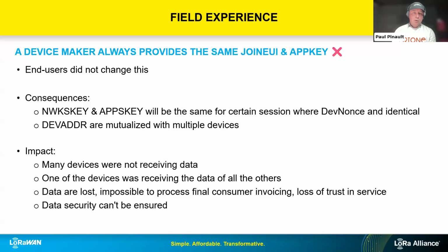And maybe you can complete this part, Julien. I mean, to obtain this DevAddr, I say it's the LoRa Alliance which distributes the DevAddr, and I think you get blocks when you are part of the alliance. Exactly. Being a member of the LoRa Alliance allows you to get what we call a NetID. So it's a network identifier, which is part of the building of the device address, the DevAddr.